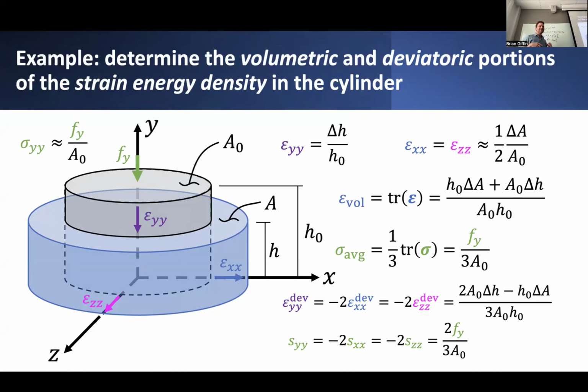Pressure usually has the interpretation of being a positive value when it's in a state of compressive pressurized loading. That's fairly typical of a lot of fluids or other types of materials that can only sustain these kind of hydrostatic pressure-like forces. And it only really makes sense to consider them under compressive loading conditions. Hence why that negative sign shows up in the definition of pressure.